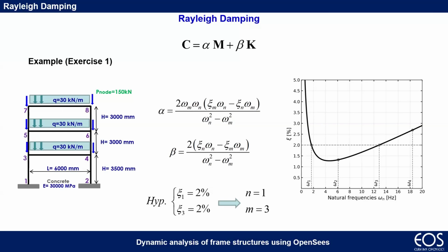The only problem that you have to pay attention to with Rayleigh damping is that since the shape is this way, if you fix two frequencies that are far away, you can find a damping lower in between. Like this.